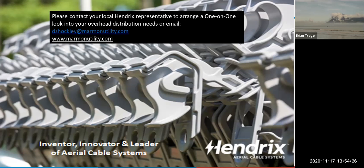Is that a safety hazard? Absolutely, positively, yes. Don't touch energized conductors. Any energized conductor is a safety hazard. Is it a mortal hazard? No. You've got 1/3 of a milliamp.